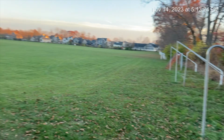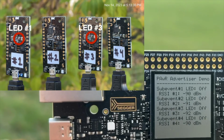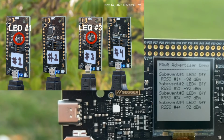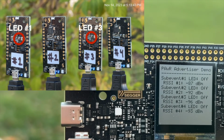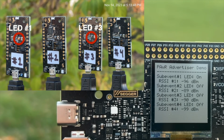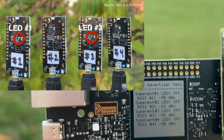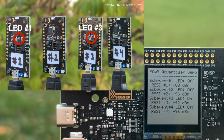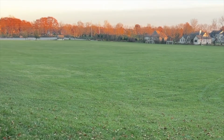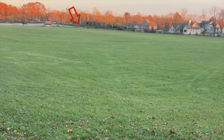Okay, this is as far as I can get, unfortunately, and as you can see here, we're still getting a good signal. So we're getting responses at minus 80, minus 90, minus 100 dBm, and if we try to turn on the LED, we can see it still turns on and we get a response confirming that. We can also turn on other LEDs like LED 3, turn it back off. And so this is as far as I can get. You can see it's all the way back there.